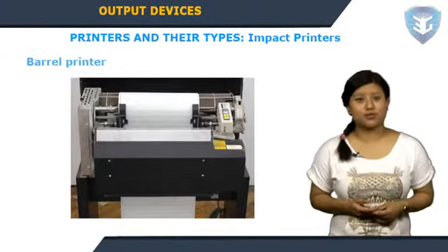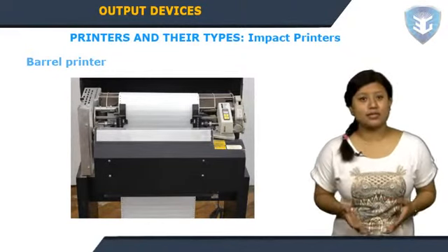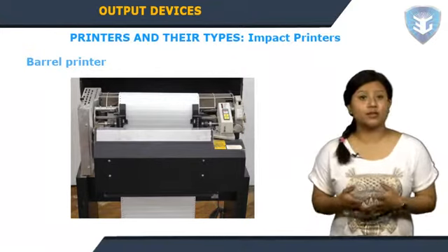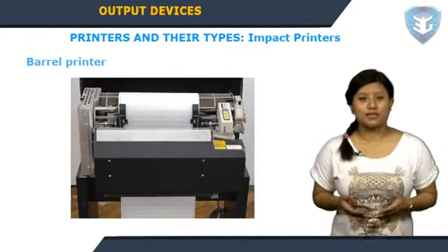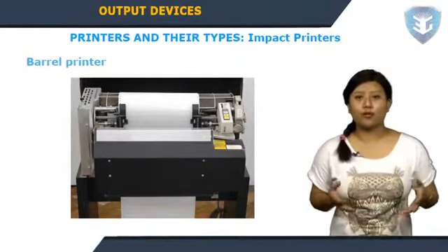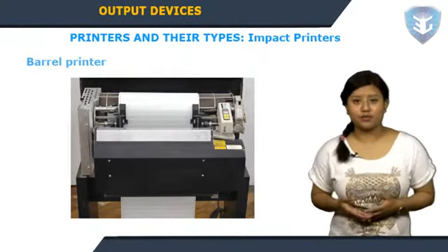Barrel printers. This printer has a number of discs, each containing all the letters and numbers. These discs are situated one near each other on a shaft and can rotate independently from each other. Lines are written by revolving each disc to the correct position in order to form a complete line. A row of hammers will strike the ribbon and the paper.